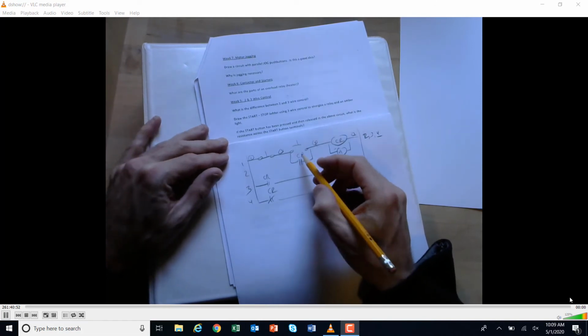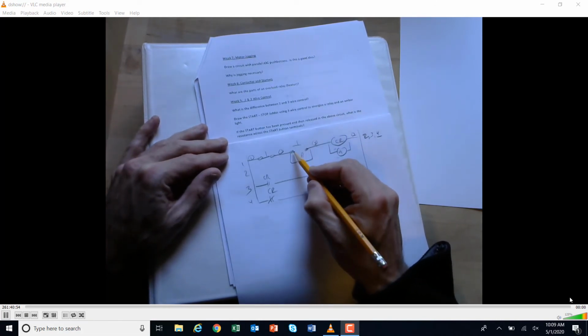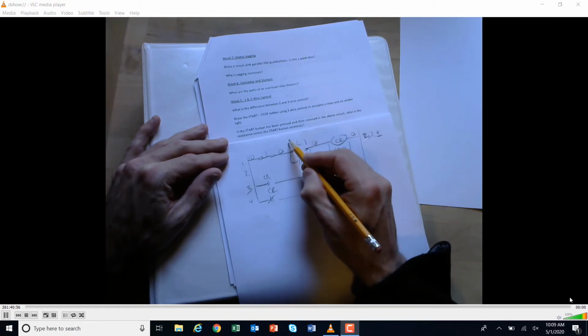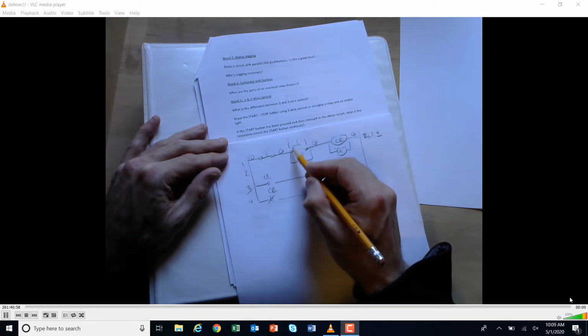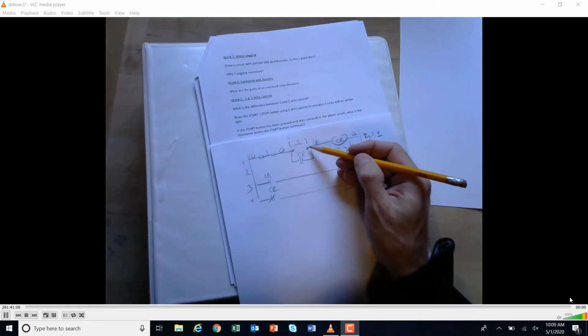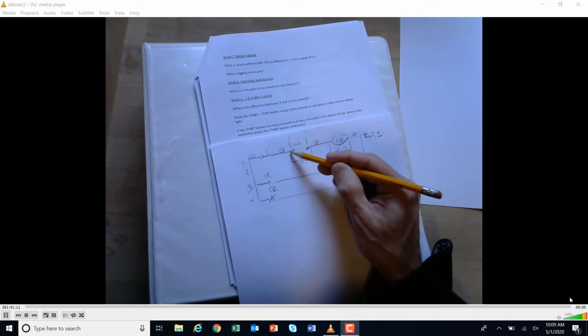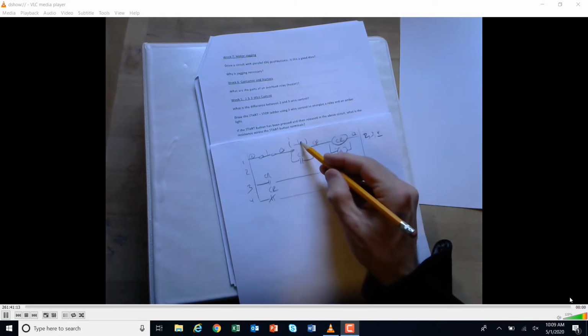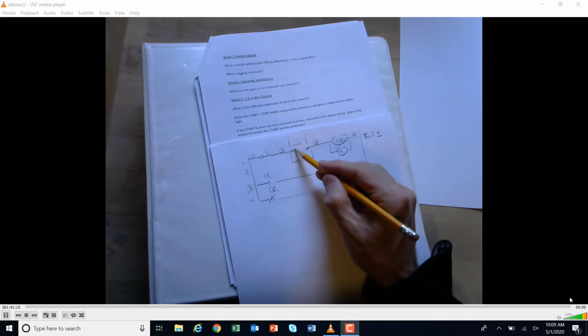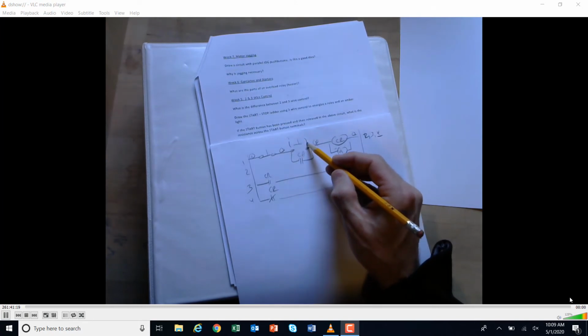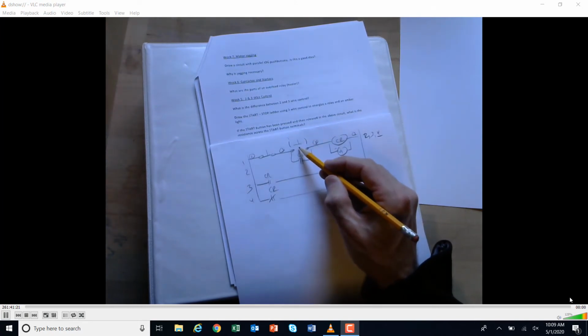So if you came in here while it was running and you tried to get resistance between here and here, that's where it's asking between 1 and 2. Well, you're not going to find any resistance because you'd actually be measuring the resistance across this here. And because this is closed, you would get 0 resistance, right? Now, if you broke this item out individually, you took this push button and it was open and you checked the resistance across that, well, that's where you would get infinite resistance because it would be open.